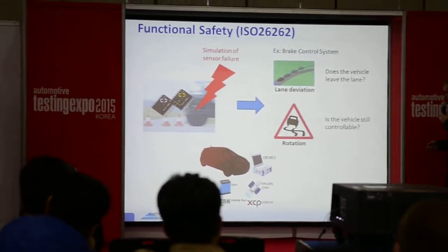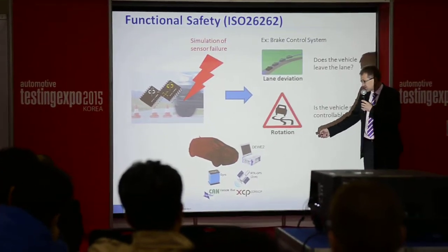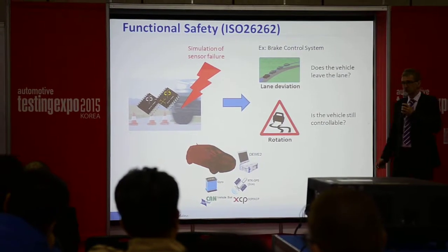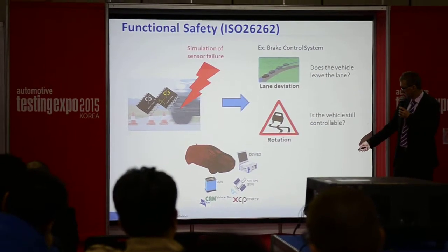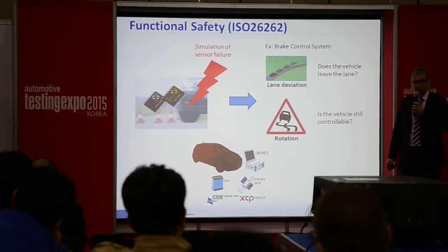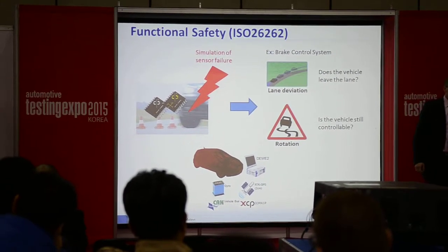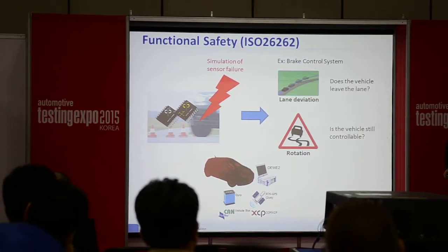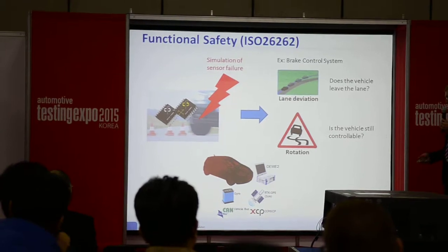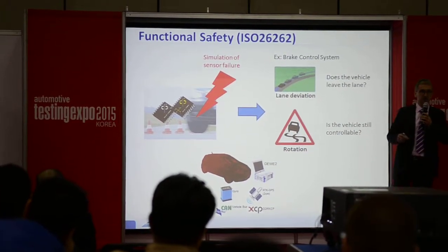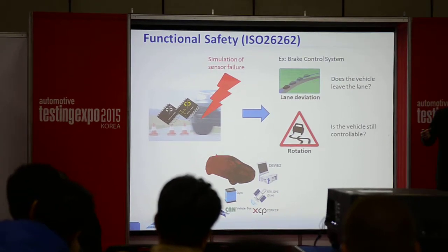The system would look like this. We need the data acquisition system, then very precise position sensing, and then CAN bus, and as mentioned before, a new thing is involved. We need to have XCP to also record ECU parameters. And XCP might also be used to simulate the errors, to inject the errors into the data stream.